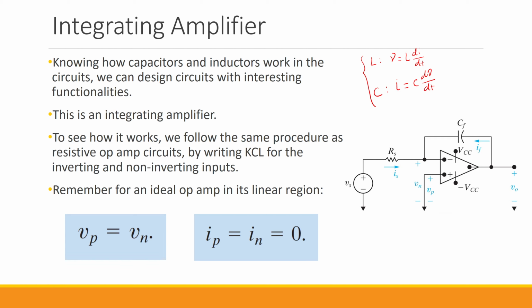Based on these equations, we can design circuits using op-amps with interesting functionalities. Here you can see an example of an integrating amplifier. If you look closely, you see that it is very similar in design to the inverting amplifier that we have seen before. Let me just quickly draw that as a reminder.